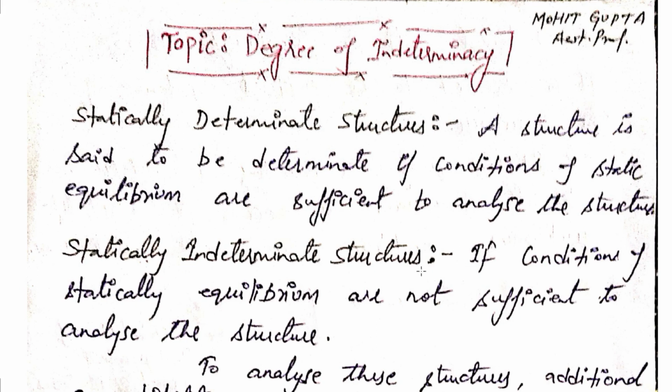Statically indeterminate structures are those in which conditions of static equilibrium are not sufficient to analyze the structure, so we need to analyze them based on additional compatibility conditions required to solve the structure.